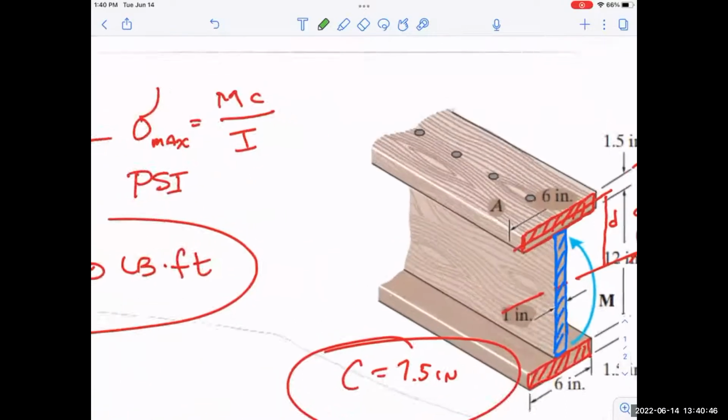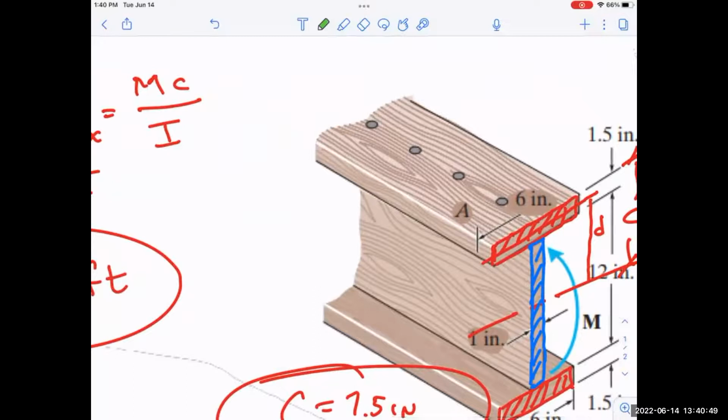Like the only part of that beam that matters is the top, because that's where the floor is. So you can add all kinds of wood under the sides and below it and kind of beef it up. You can glue a whole bunch of stiffeners in kind of inside in this area. Does it make sense if I added another board kind of right through the middle of that, running back here? That could stiffen it up a little bit. That'll help. Or maybe I add some chunks right there and glue it together and so forth and make that top web longer and run it for a distance way down the board, so I can beef it up a little bit. So yeah, there's things you can do to fix it.